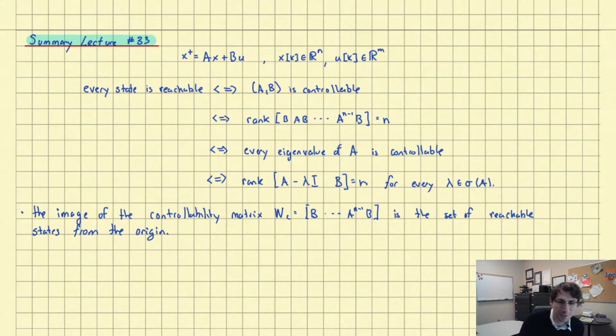Okay, so we have been looking at direct design of digital controllers. This is where you discretize the plant using the step invariant transformation, and then you design the controller in discrete time. The advantage of doing that is that you can account for possibly large sampling periods and get performance guarantees, at least at the sample instances.